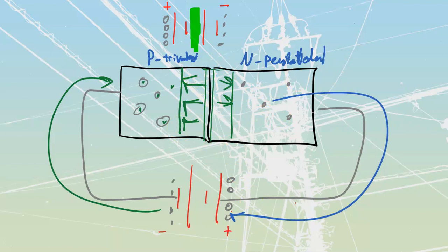This fundamental item that we have drawn in over here is going to be our diode, and we've taken a look at this inside of first and second year. A diode, which we're commonly going to see drawn like that, tells me that this line over here is my N type of material, and this line over here is my P type of material, with the arrowhead inside of here. Forward biasing and reverse biasing a diode works to either give us current flow or to interrupt current flow. It becomes basically a one-way valve for current flow.